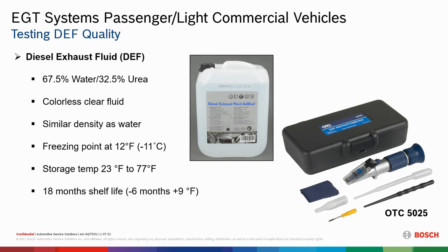And that's where the test tool comes in. We see this OTC 5025 refractometer that can be used for testing. Even though some of them have quality sensors, could there be a problem with the quality sensor? It's not a bad idea when you take your sample to test the fluid anyways, to see if everything's working properly. It's a colorless clear fluid, similar to the density of water.